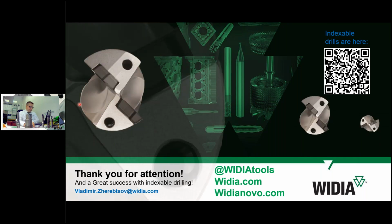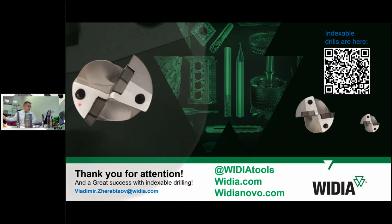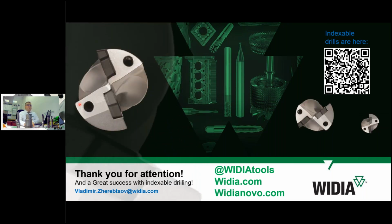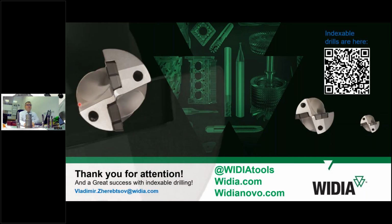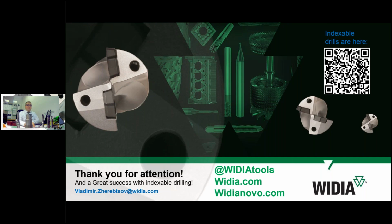Okay, perfect. Thank you. And is it okay, Vladimir, to use indexable drills for dry cutting or without coolant? Basically, yes, but it's more or less reliable when the depth of the hole does not exceed 1 diameter. It's possible to use up to 3 diameters, but usually only on horizontal machines. It's better to try with coolant to avoid dry cutting.